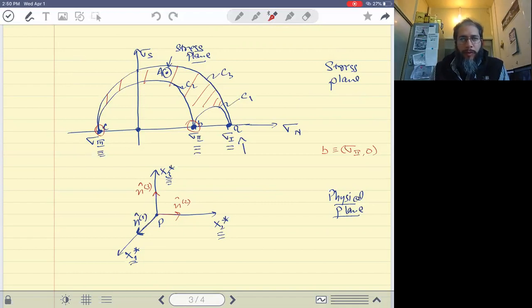the sigma n axis. Now remember, feasible stress region is the red shaded region. Okay? So the red shaded region intersects the sigma n axis at only 3 points, A, B, and C. Now, what we usually do, because we have to figure out the normal direction, it's easier if we draw the first octant of a sphere centered at point P. So what I mean is, I will quickly erase these normal directions just for clarity.